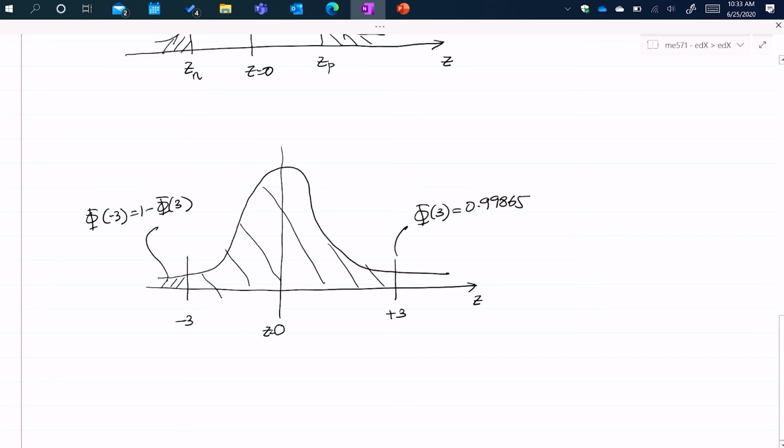Normally, with any manufacturing process, we have something that we would describe as process capability. We would say, what if I had a tolerance limit and the manufacturing process gives me an ability to achieve the tolerance limit to within a plus or minus 3 sigma capability. In other words, this is describing the manufacturing capability.